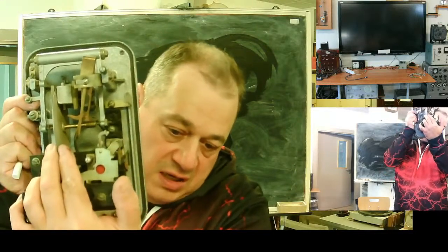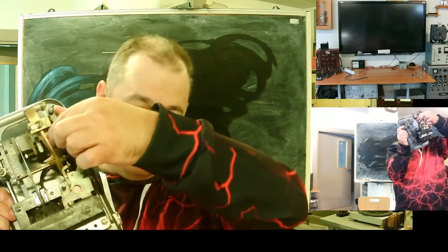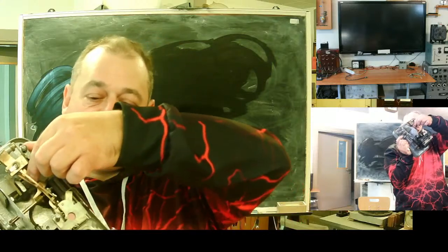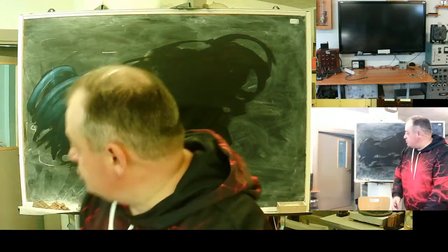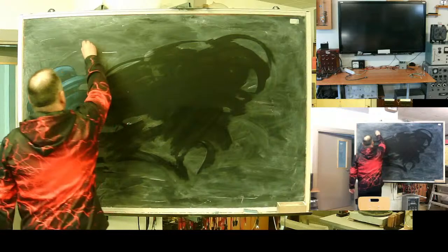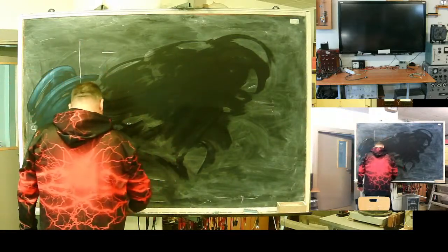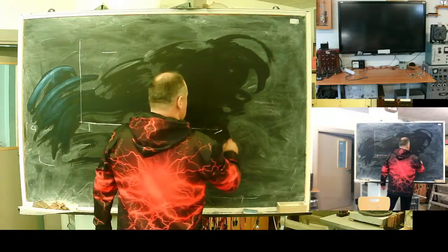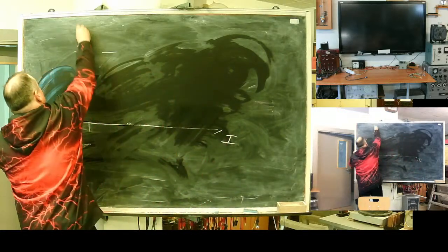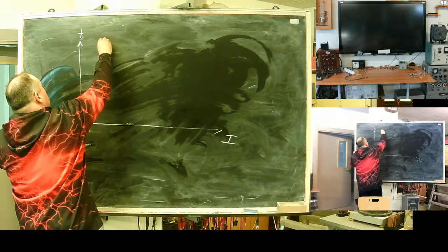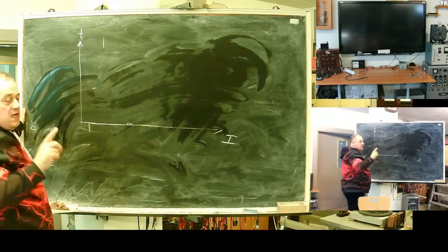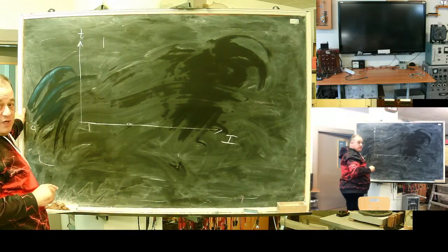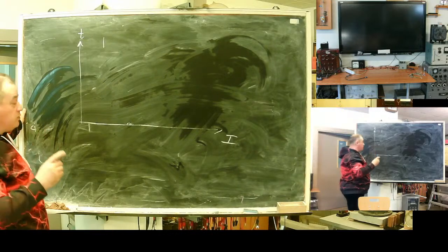I hope you can see. The disk will come into junction with this toothed arm, lift it up, and send a disconnection signal. So this relay will have a characteristic current-time curve like this, until the arm is connected to the disk. Time will be infinite. It will simply rotate without any effort.